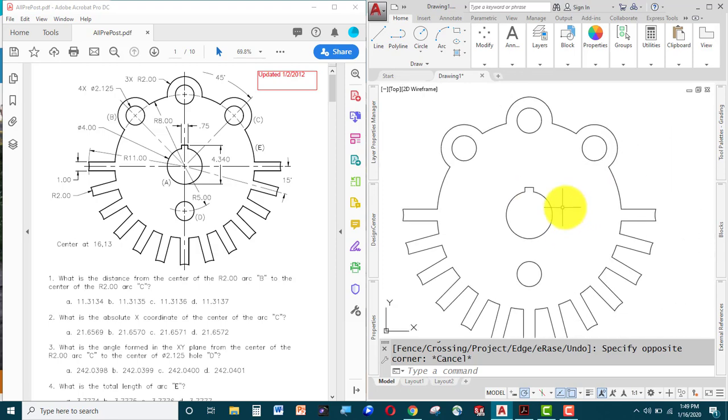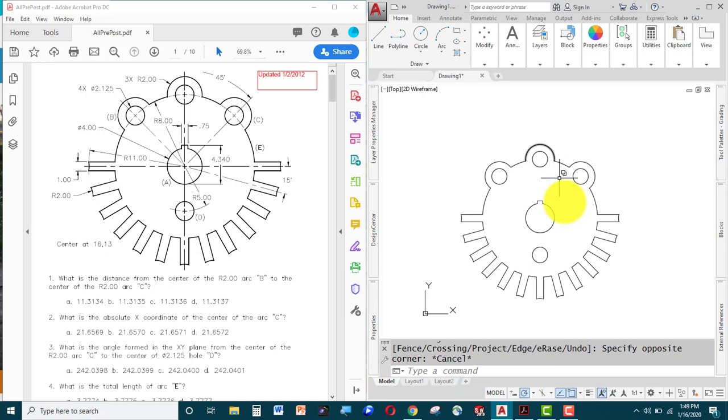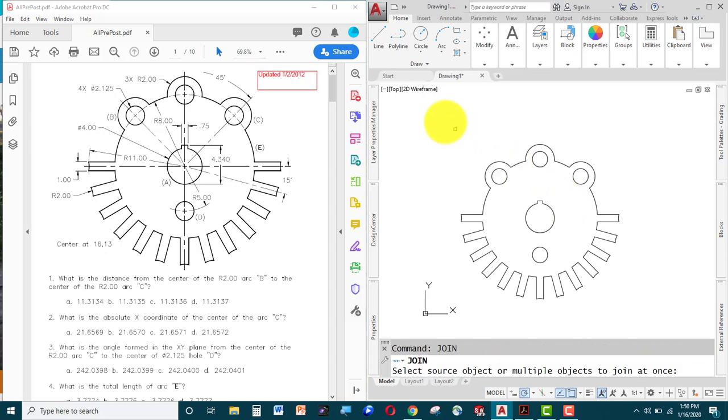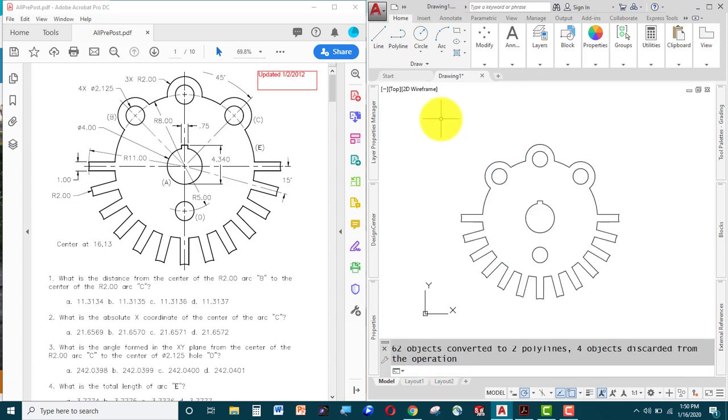Now, one way to check to see if you've got drawings that are accurate in the sense that there are no gaps at the intersections, that there's no overlaps, is to join things into a P-line. I'm going to do that using the AutoCAD join command, and I'm just going to put a window around, or type all, everything that I've done and say join it all together if you can. If I come down here and hover over it, that now becomes one entity, that becomes one entity, and that gives me some reassurance that there are no gaps and no overlaps in any of the corners.